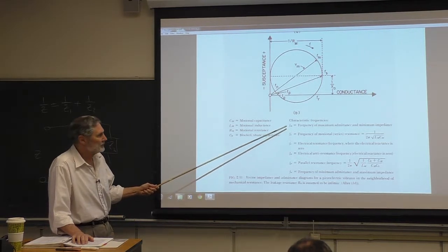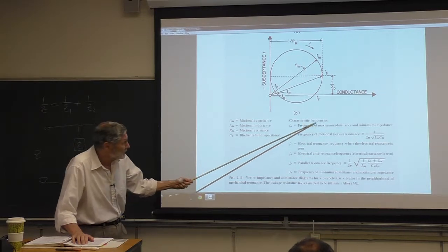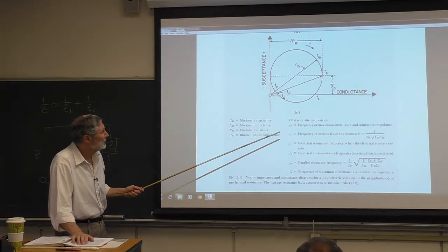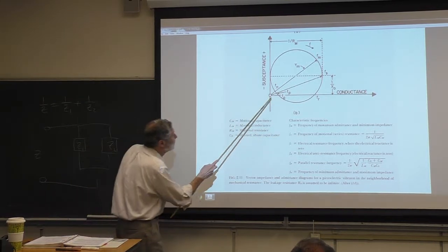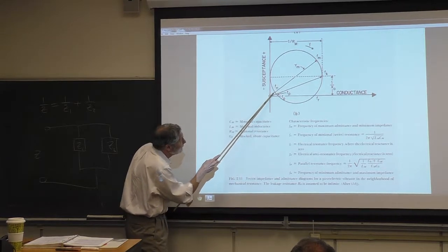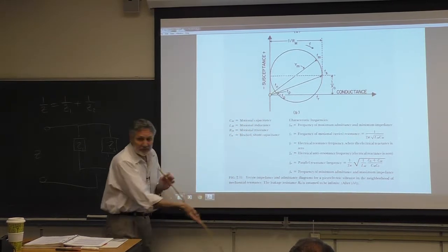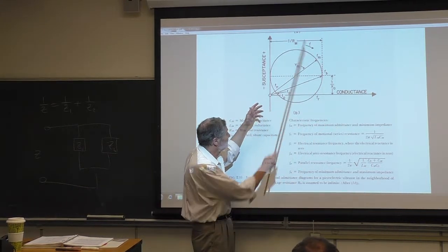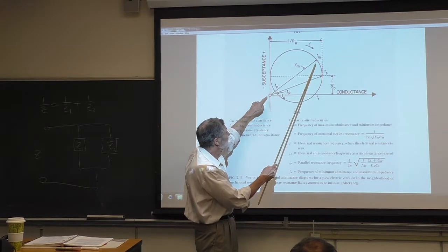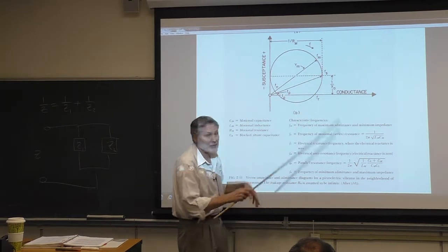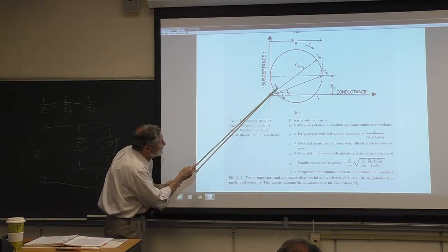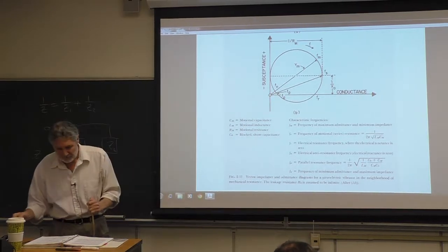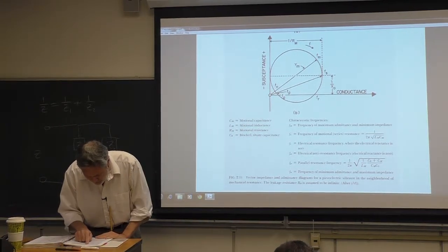With every resonance, there's going to be an anti-resonance. The anti-resonance here is going to be the arrow with the shortest length. Can you see where that is? That's going to correspond to the diametric arrow right here. Now, for the impedance, they'll be flipped, because the impedance and the admittance are reciprocally related. Where you get the maximum here, it'll be the minimum for the impedance. But this F sub n here refers to this point right here. It's just that right there. Okay. So, yeah, I'm going to follow the notes here.